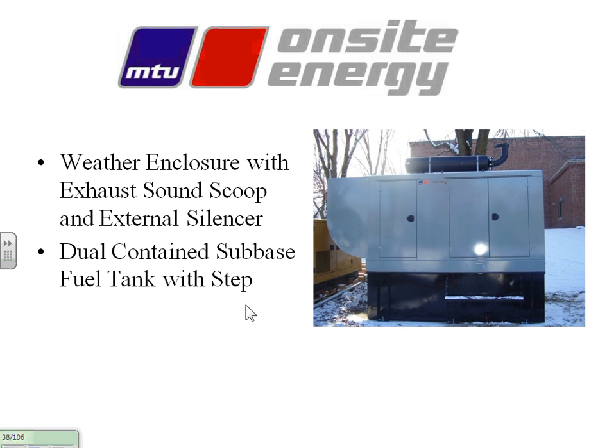Another style, this is basically what we could call a semi-sound attenuated unit. Here we have the muffler on top, so it's just a little different design, and it's nice to get the exhaust pointed up and put a rain cap on it. Down in the bottom, I'm going to point out a couple other things here. We're going to talk about noise in a little while, but while I'm here, I'm going to show you. Remember I said this is a pusher type fan. So it's pushing the air out here, and the scoop is going to direct that air up.